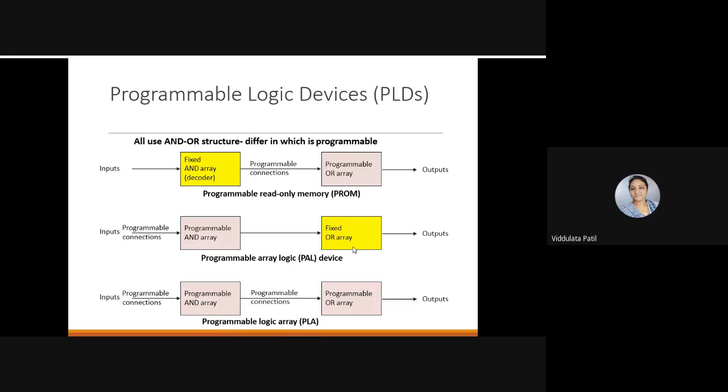So this is the same as the table we have seen earlier, now in terms of a diagram. Then in a programmable logic array, both the AND array as well as the OR array are programmable. That means whatever connections we have can be changed or configured in different ways. So this is about all the SPLDs: the programmable read-only memory, the programmable array logic, and the programmable logic array, that is the PLA.